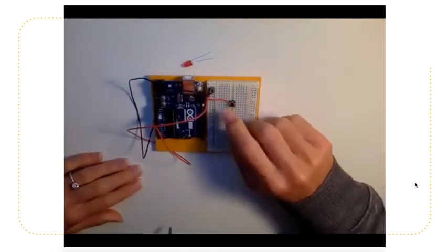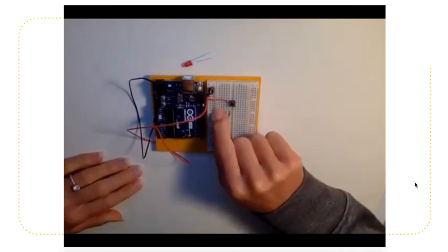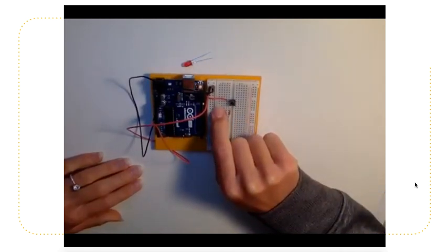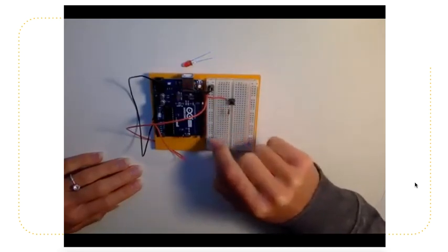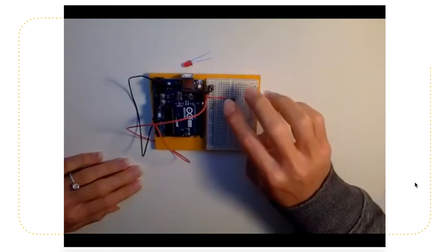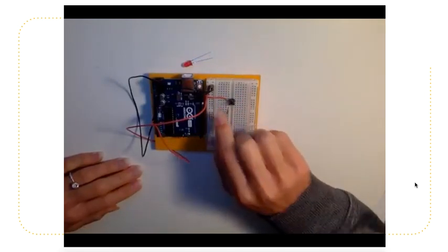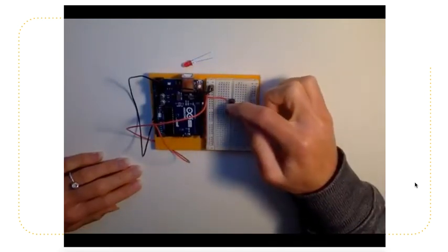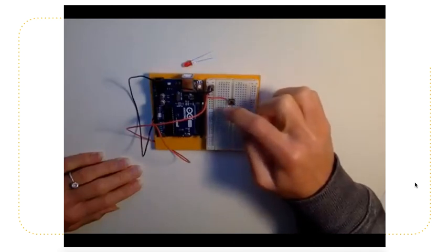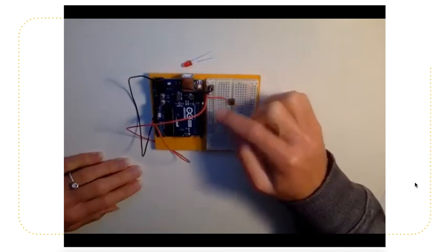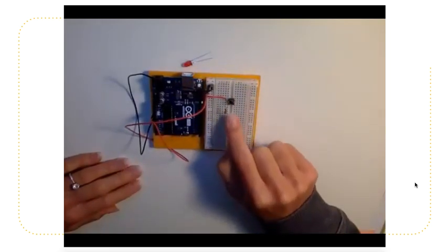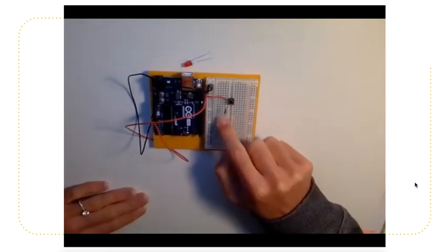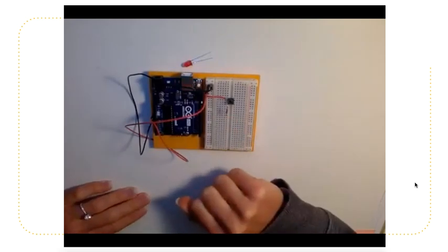So now if we're tracing power, my power was in row 9. I know it's really hard to see because they're small numbers, but there are numbers and letters on your breadboard that tell you what exact position your piece is stuck into. So right now on this side of the resistor, the power's running through row 9, and then by putting the resistor in vertically, I'm transferring the power to row 13.